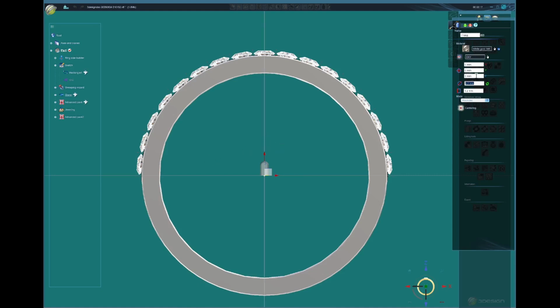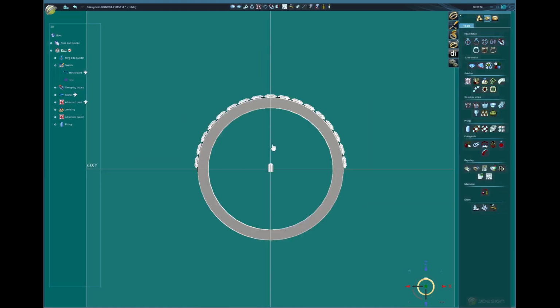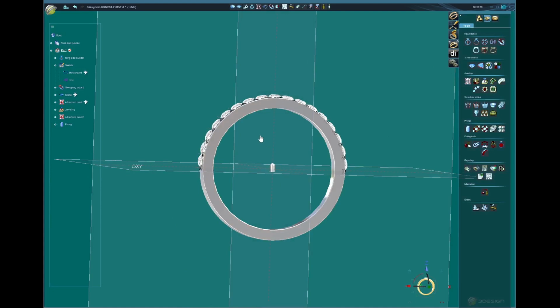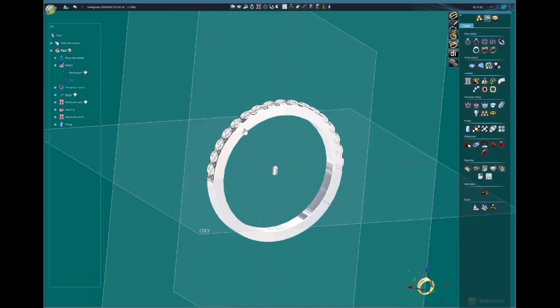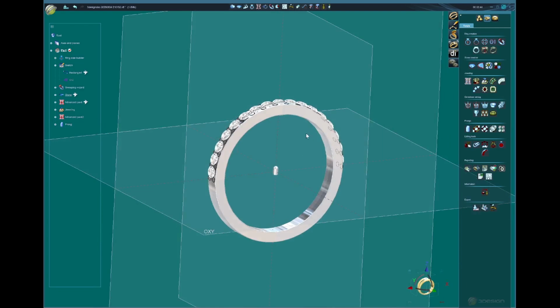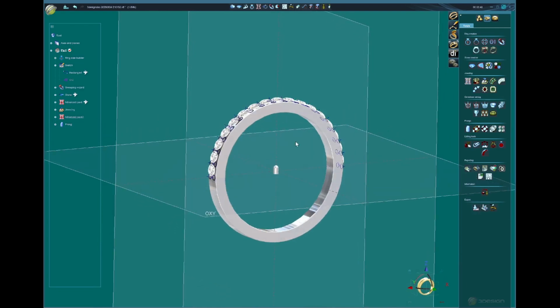Usually I do 1.2 millimeters and I do minus 0.4 millimeters, which is going to bring my prong down. See, it came down, and I'll click OK. So with that, I'm going to leave the prong here, because when I put it over there and you see that the prong is sticking out too much, you can change over here and see the right position for your liking. So let's click the prongs.